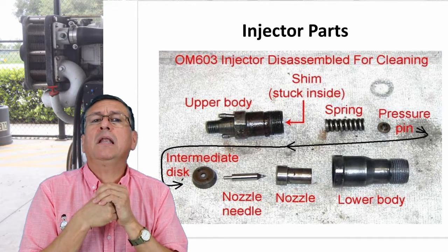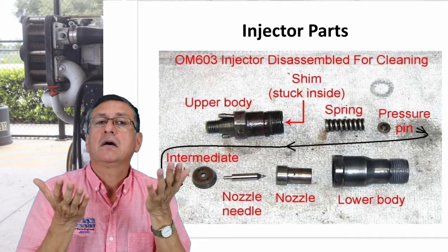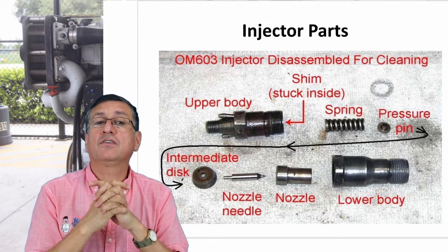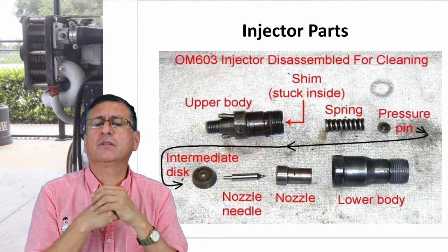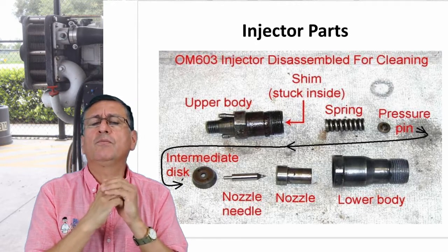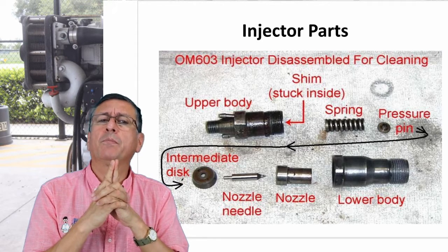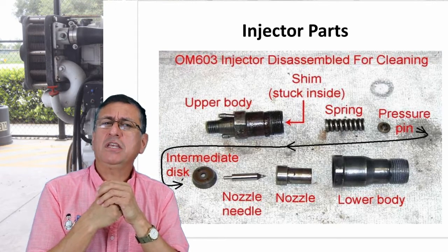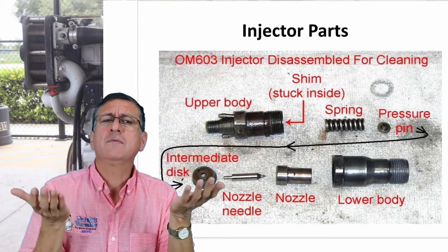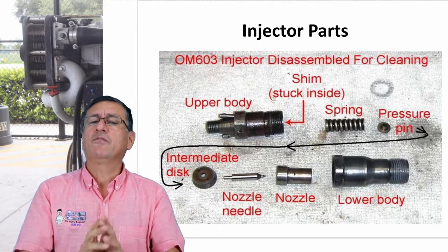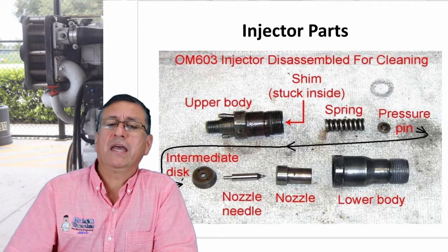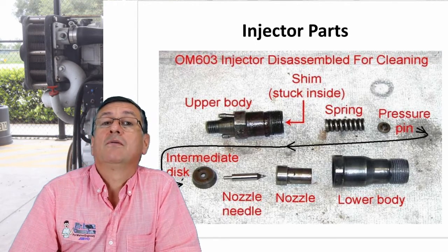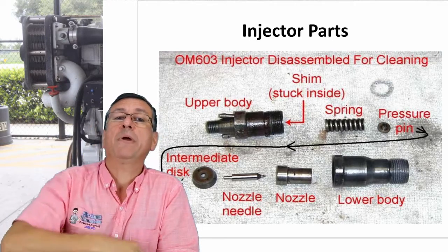Normally, in what cases do I need to do a service on the injectors? Normally it's mandatory each 1000 hours, or depending on the manufacturer recommendation, and also if the injectors open improperly, or if the injector stays open all the time. What is the consequence, or what are the symptoms in those cases? For example, what is the symptom when this spring is broken? If the spring is broken, what happens? The injector stays open all the time.